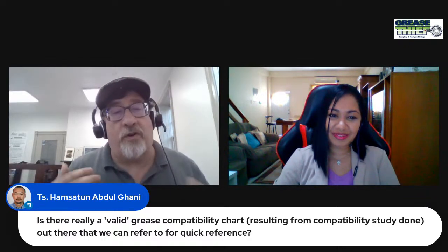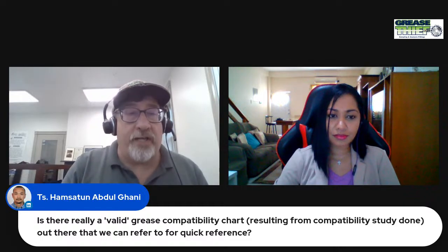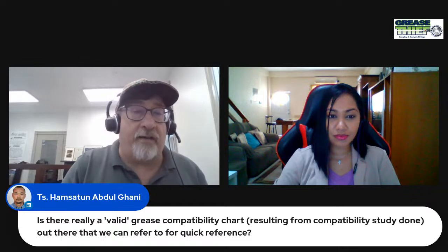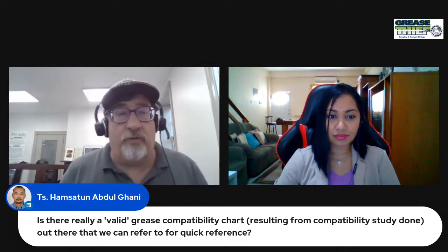So I'm not going to say there has never been a valid grease compatibility chart. What I would say to those who would utilize them or want to utilize them is ask those fundamental questions. How was the data determined? And does it look at all of the compatibility concerns that I have for my application? And if I'm satisfied, then I can use that and move forward.